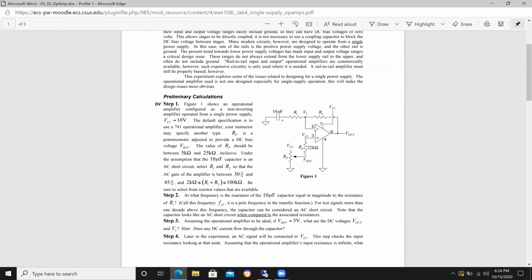So what you're going to have here is this VCC down here on your potentiometer is the same VCC, 5-volt supply, that's supplying your op amp. The potentiometer will have a little screw on it, and you'll have almost like a jeweler's screwdriver in your kit, a little flathead screwdriver, and you're going to turn that knob, and this wiper is going to go up and down. This resistor right here is acting as a voltage divider, okay? And you're going to set the voltage right here to be VREF at a particular point. So that's going to set your DC bias.